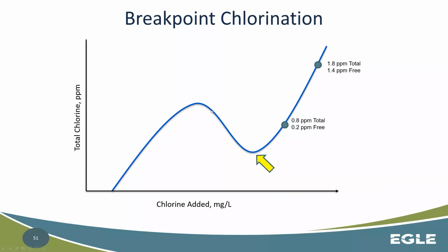So you're burning up any ammonia that's in the water, some other issues that are in the water that chew up chlorine. You're burning through those things. This area right here is why you get complaints around a pool type odor or smell in your drinking water associated with chlorine. You keep feeding chlorine, you'll actually get to the bottom of this.